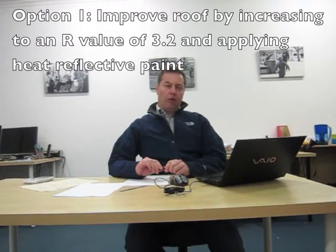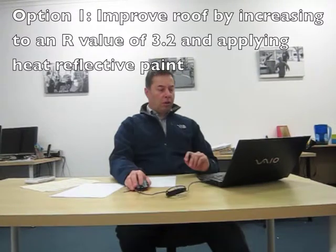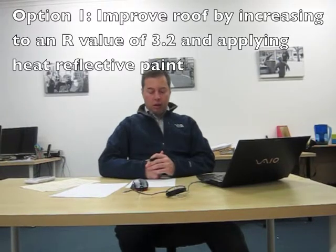Following the construction of the base building, the original building, we played around with a couple of options. The first option that we looked at was increasing the roof insulation to an R value of 3.2 as part of our building fabric recommendations.